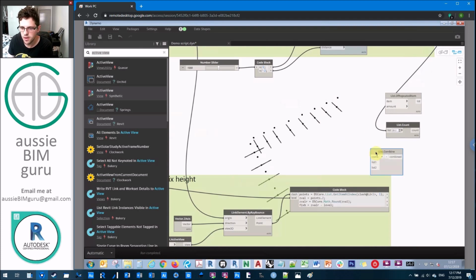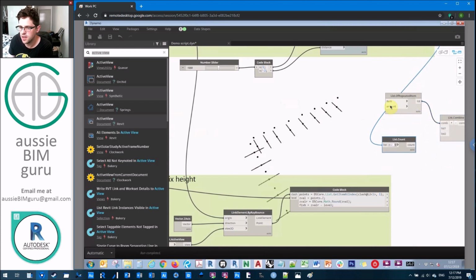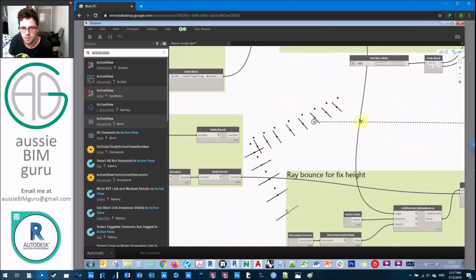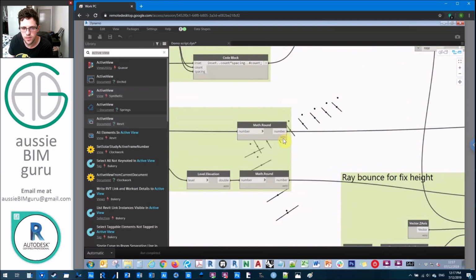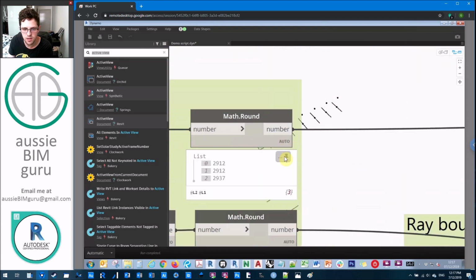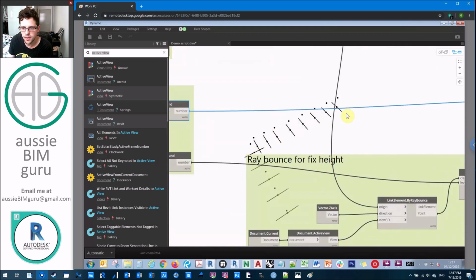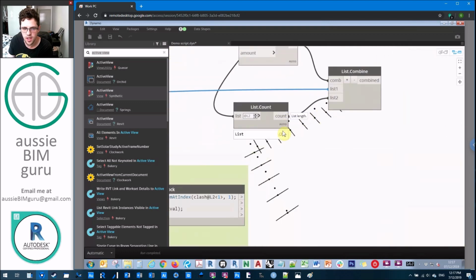So we want to repeat the elevation. This is our combination function, and then we're going to be feeding in our count as our amount. For our items, we're going to be getting them from our elevation. The way that list combine is going to work is it's going to say for each of these items, apply this function at the same level as each of these counts.